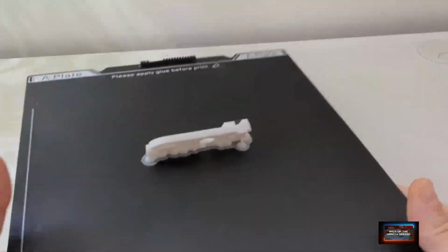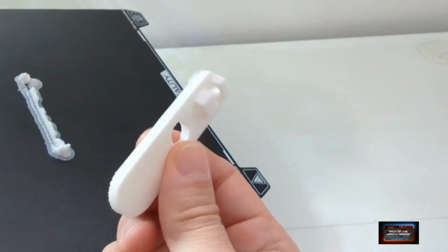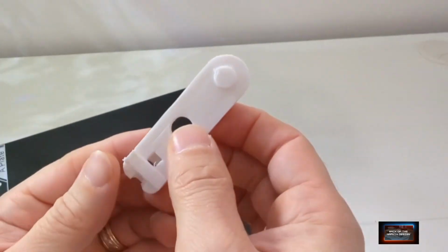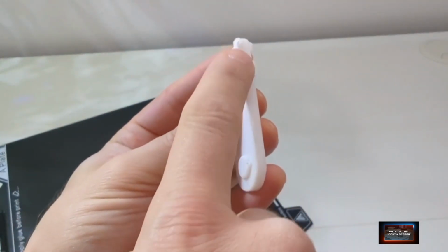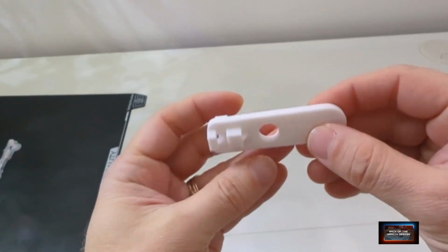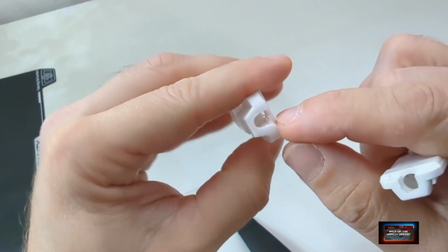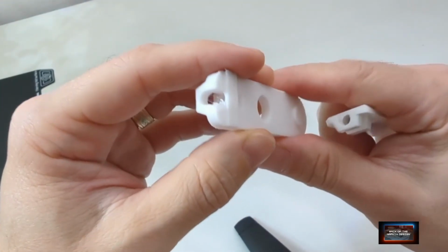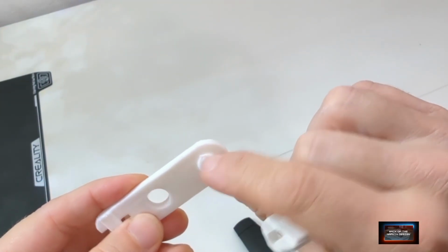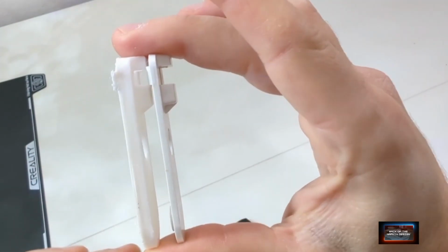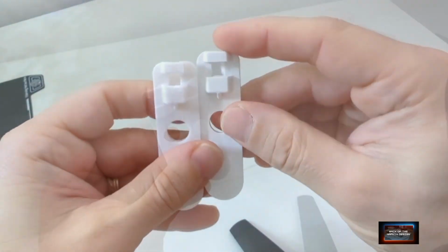I have the 3D printed part right here. I'm going to take it out. It just popped right off. So let's take a look at this. We got some things we got to clean up here. Everything else looks really good. I must have doubled the thickness somehow. And there's a lot of stringing going on inside of there. That's kind of goofy there. Besides the thickness, I would say nearly identical. I'll fix the thickness and reprint.